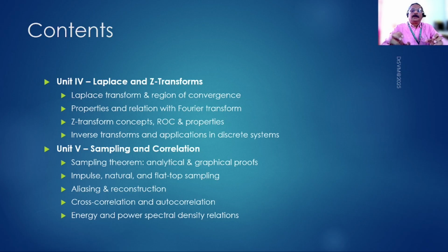So we analyze a given system and then look at what conditions there are zeros and what conditions there are poles. So now we can start talking about a system more mathematically in terms of zeros and poles, and that is possible only through what we call Laplace transform. This Laplace transform is basically used for continuous domain signals, but if you convert that into discrete domain, then we need a different transform which we call Z transform.